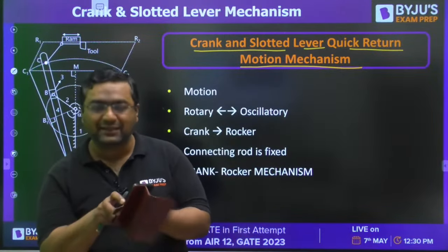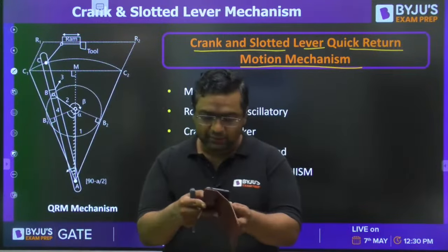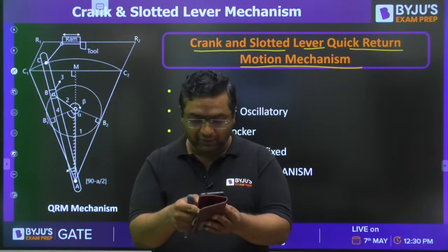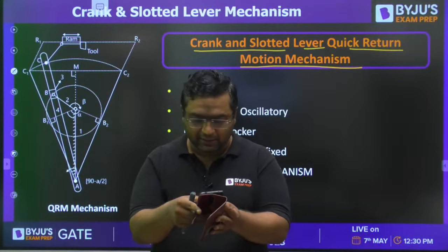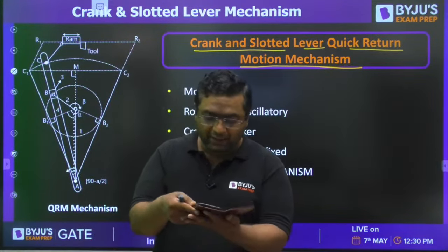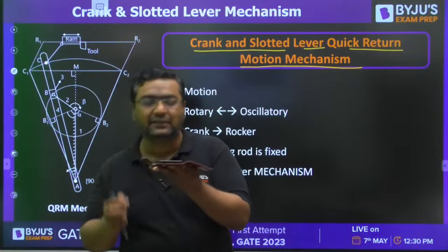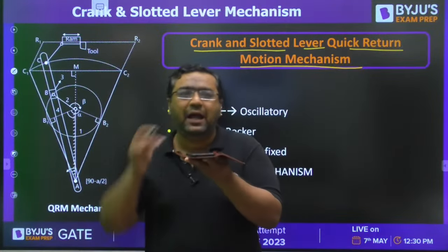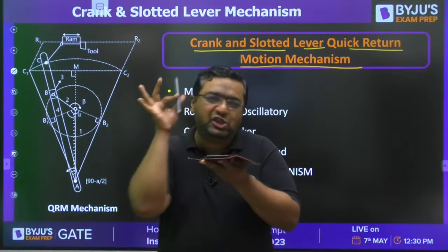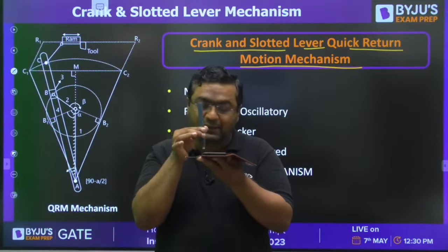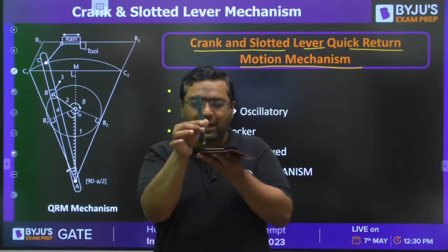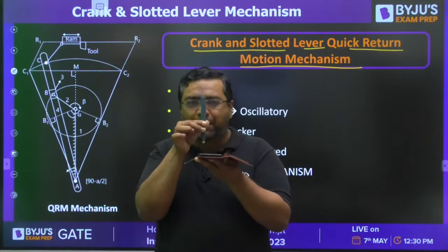Okay. So to understand the meaning of this mechanism, I am showing you something. Just look at it. Let me just lock this phone. Now my dear, you can see this is nothing but our plate, and I want to do machining on that. This is my cutting tool. So in shaper and planer, what is going to happen? This tool will be passing through this workpiece and machining will happen, and it will be coming back idle.